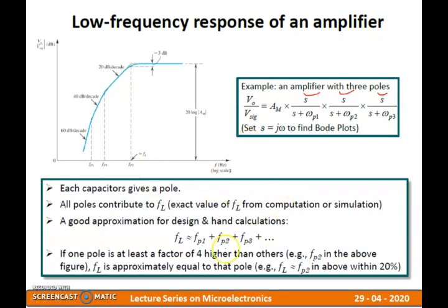So this is the general picture I try to give for the low frequency response, wherein you compute the different values of capacitance and arrange them in the form of a transfer function. Whichever capacitor, because of which the frequencies or the gain is getting impacted largely, that particular capacitor will be playing a vital role in the determination of the gain.